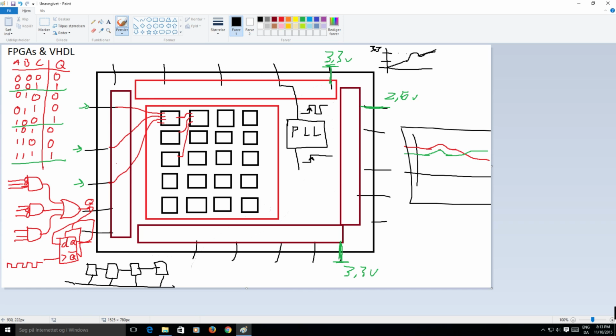So if you, for example, want to divide the input clock by 37, it would probably be better to use the PLL than to make it in hardware. If you were to divide it by 8, it wouldn't really matter that much. And by the way, I'm not saying that it will not work if you're doing it in hardware, because there is a lot of headroom, and depending on your clock speed, of course, it can be more or less. The slower the clock you're running, the more headroom you'll have, of course, before you start to get into problems. So there's probably still something that I forgot, and if there is, then we will get back to it later.